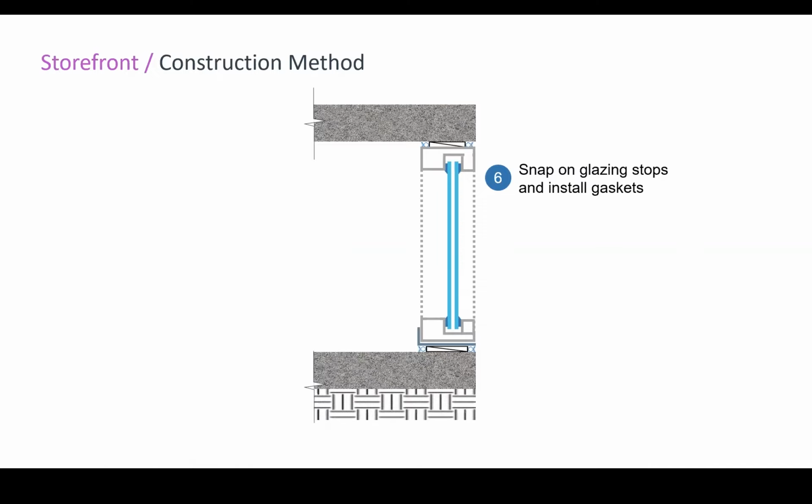So storefront systems are exactly what you think of when you go shopping at an outlet mall, or perhaps window shopping. You're going to see these systems typically installed in those types of applications. And typically a storefront, you can tell because it's contained to the first floor, but can span up to 2 stories. But it usually does not go past that.